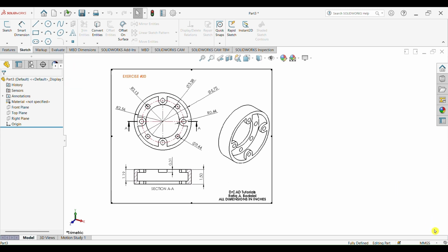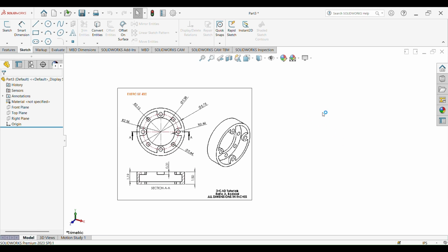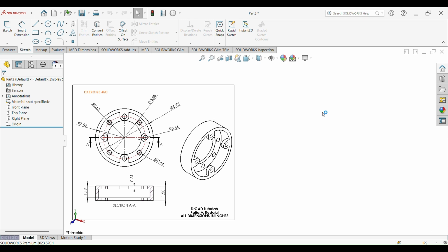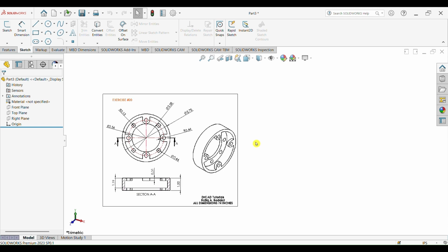So before we begin, we go down here, and we change the unit system within SolidWorks. Currently, it's in the millimeter, gram, second system. We're going to select inch, pound, and second system for this exercise. So go ahead and select that. Now, whatever line, circle, or geometry we draw, the dimensions are automatically going to be in inches.